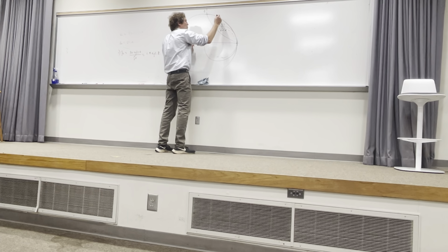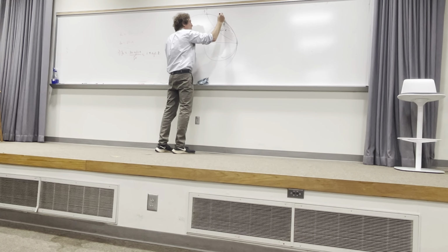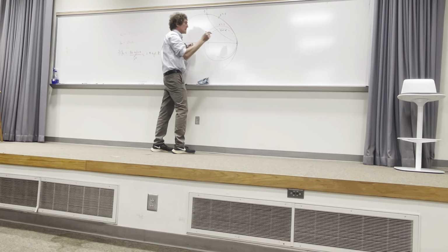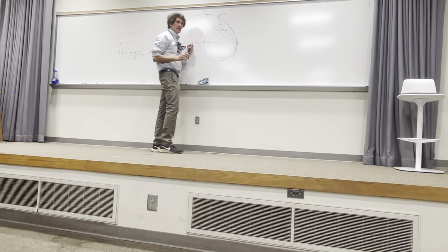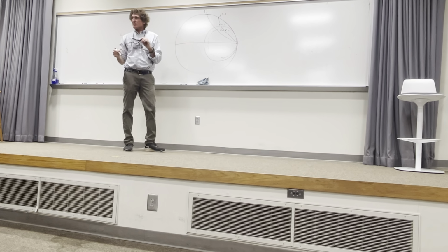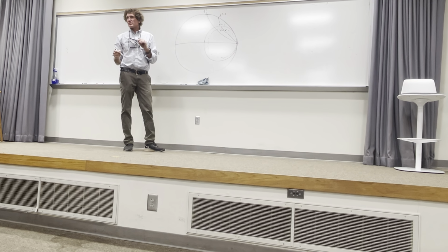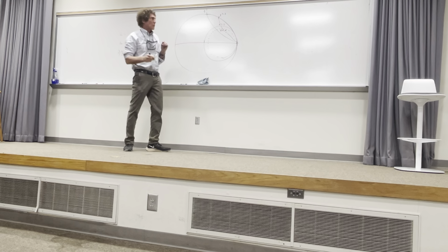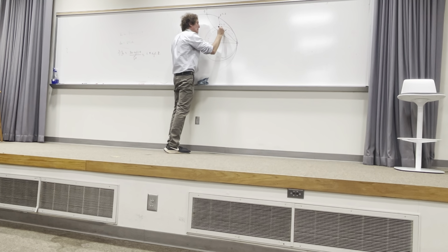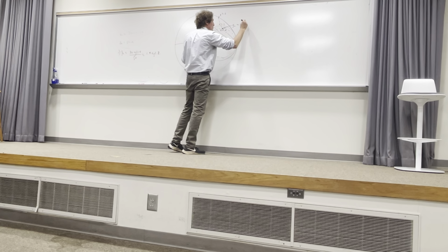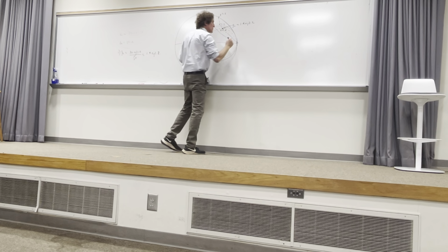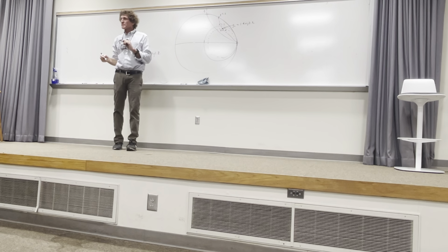So if this is j1, j2.2, I'm guessing, is about there, and it'll be a trajectory like this. Just make sure y'all can see this. Pick your Smith charts out, I'll give you a second. Locate this first point. The intersection of those two lines is your first point. It's ZL, which is 1.4 plus j2.2. Can you all see that?